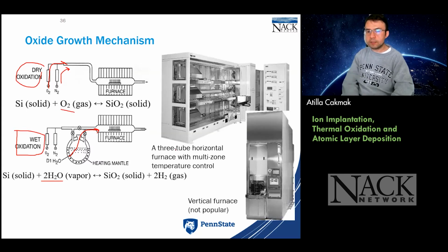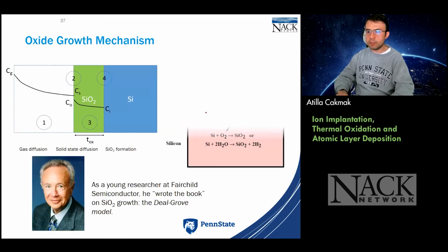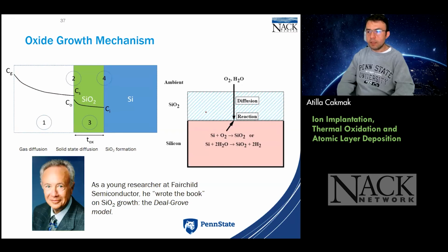And these are the general tools and how they look. Very similar to last week's CVD presentation. We have horizontal furnaces or vertical furnaces. But unlike the case with CVD, where we might be favoring the vertical furnaces even though they're more expensive, most of the time people go with the horizontal ones in oxidation furnaces, as far as I've seen around me.